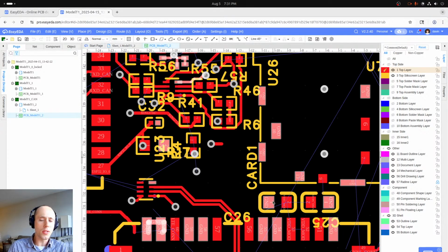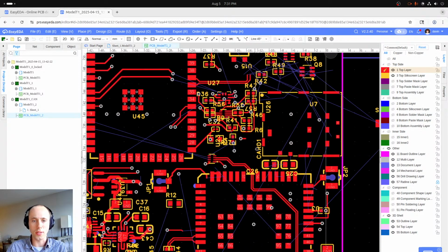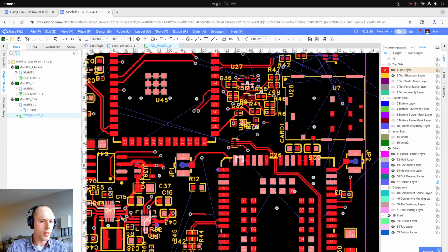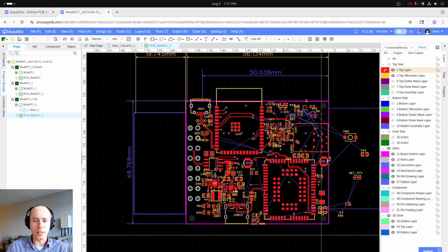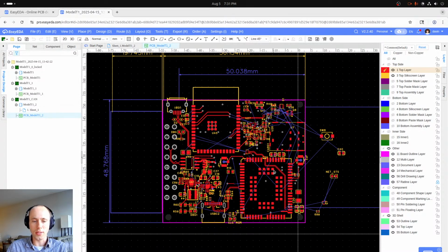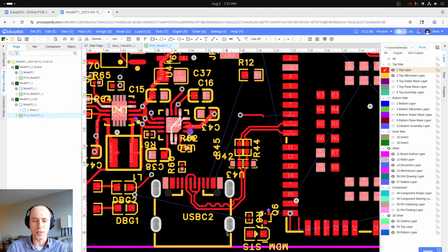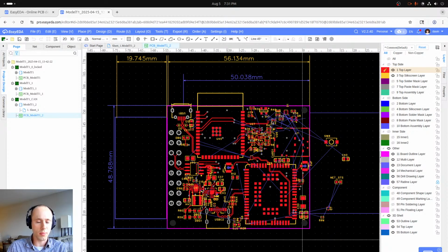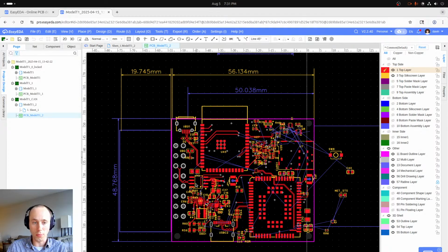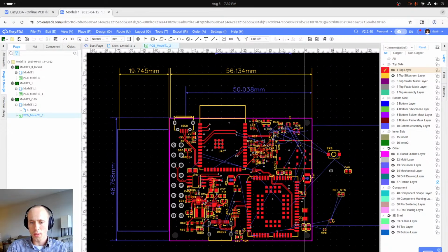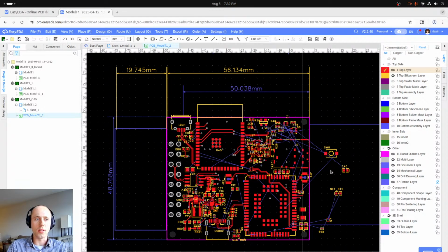And when you're moving components around like that, especially on a cramped board like this, it's not wise to be doing the routing at the same time. You really want to just focus on placement, making sure everything's in the spot that you want, at least generally. From there, you start doing your routing.